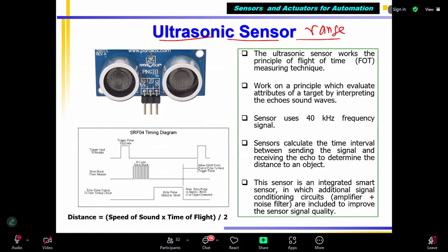When changing lanes, you have to see whether a vehicle is nearby in the next lane, between two vehicles, maybe 4 to 5 feet, or only between two vehicles in the lane, between two lanes. So you can use ultrasound or infrared. But if you want to measure long distance, you can use laser or lidar or infrared.